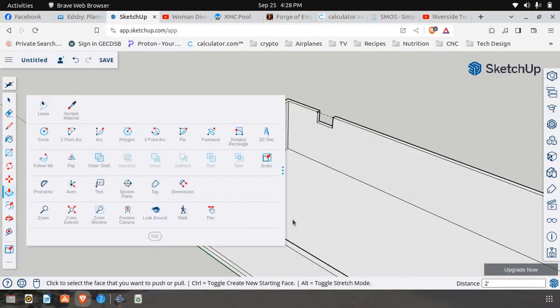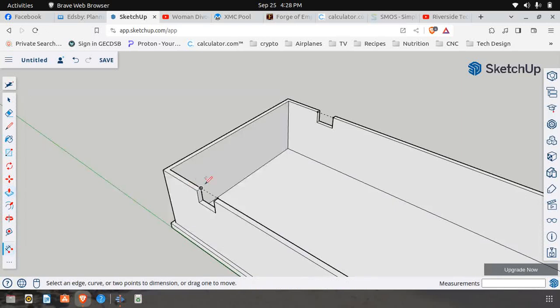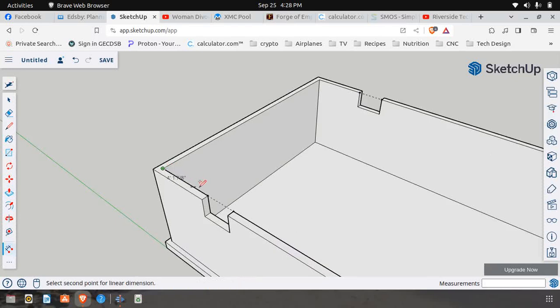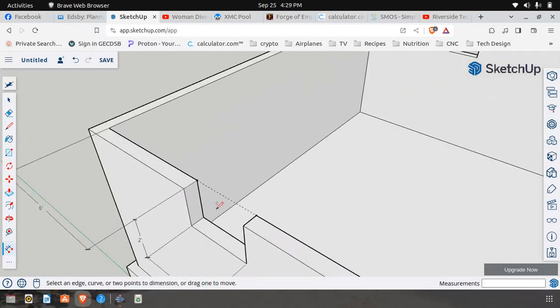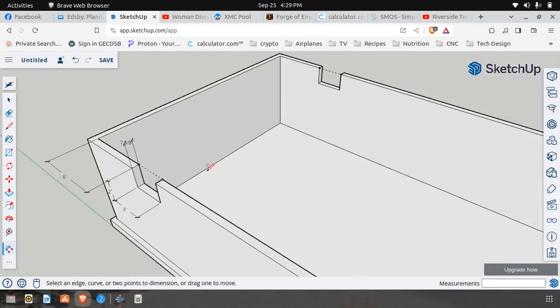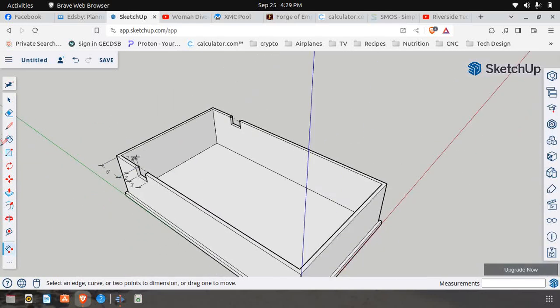So I'm going to create the dimensions just for that one. Definitely dimensions, if something is repetitive, especially if something's typical, you're definitely not going to have to show that over and over again, okay? So there we have our 6 foot. There we have our 3 foot, our 2, and I would include our elusive 7 5/8. Okay, now everything else is good.